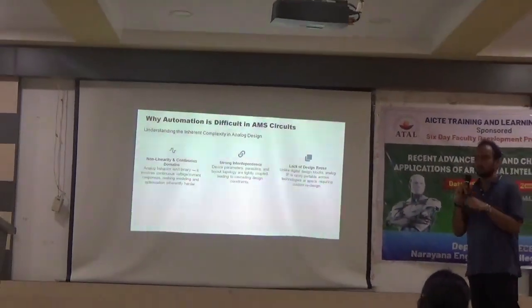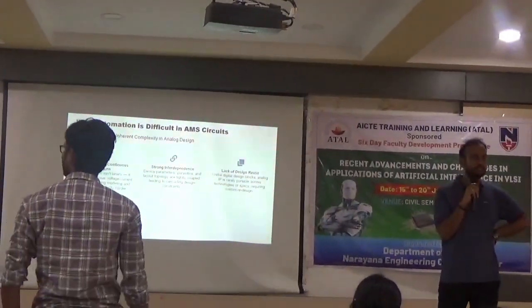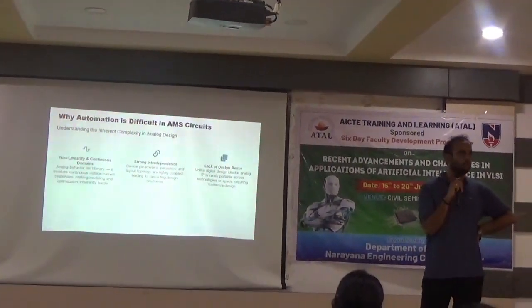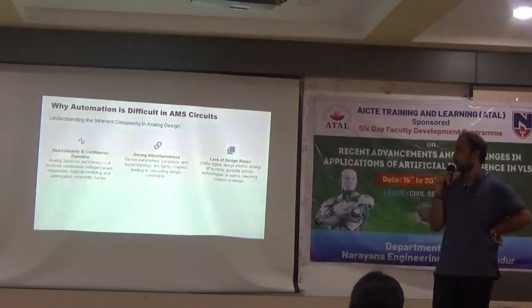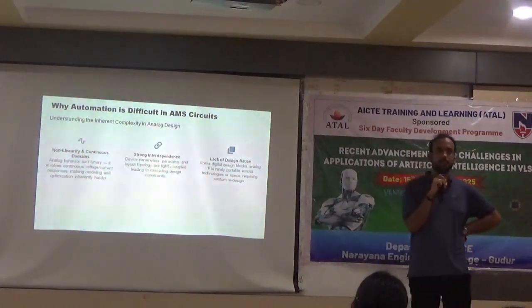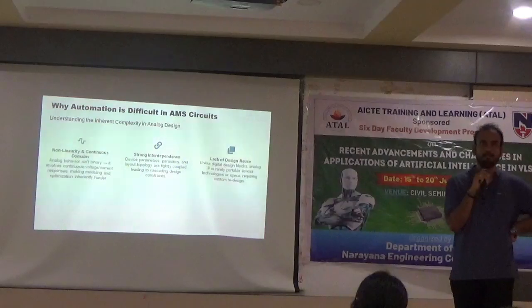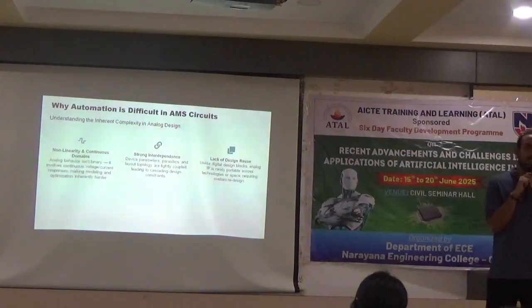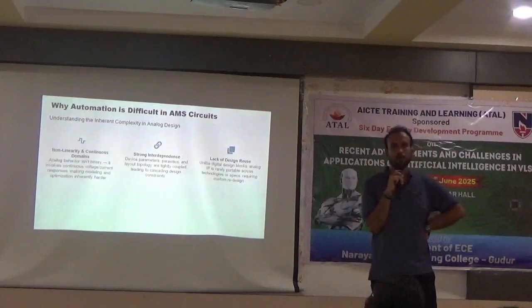As I told earlier, analog is not very trivial. It's not easy compared to digital, I would say, because it requires a lot of knowledge on the analog side, and there are a lot of parameters, a lot of topologies, also the device models and the parasitics associated with them, layout challenges, and the floor planning. All those things we need to take into consideration while doing the analog design.